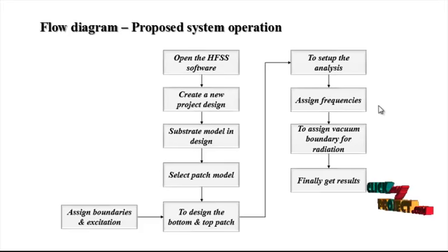Let us discuss the flow diagram of the process. This is the overall flow diagram and the structure. First of all, we should open the HFSS software, the High Frequency Structure Simulator, and then create a new design. Whatever it may be, we design. A new blank page will be displayed.